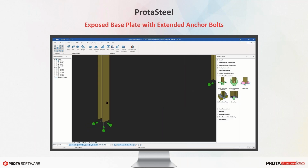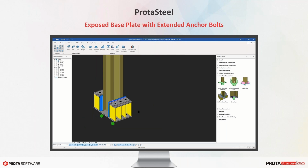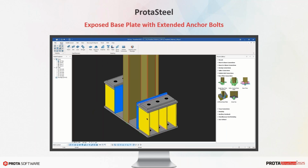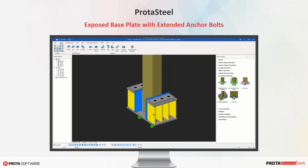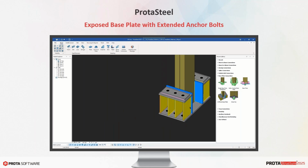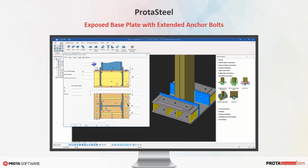Column-based connections are one of the most critical components of special steel moment frames. Traditionally, exposed base plates are preferred for low to mid-rise buildings, while embedded base plate connections are the norm for larger, taller buildings. This type of connection is common in seismic areas such as Chile, especially for industry facility buildings.